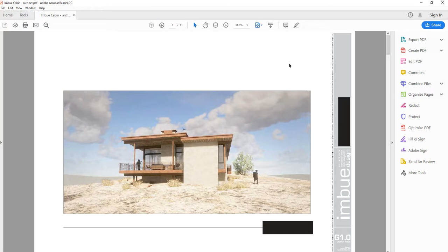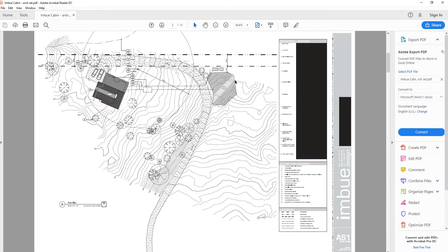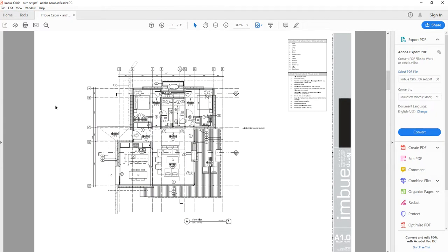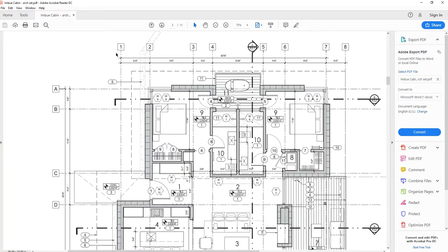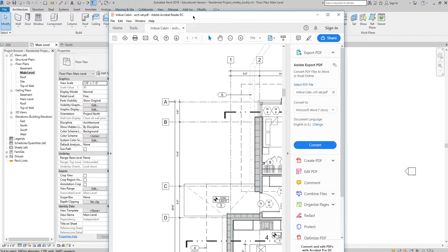And you've all taken a whack at getting some walls drawn in here. But what would have been really helpful is if you had known, and I knew this going into it, you wouldn't know how to draw grids yet. But going into it, grids would be very helpful, right? So a lot of these walls are really kind of defined off this grid. So how do we use that grid? Number one, how do we draw it? And then how do we use it to help us draw the walls in the right place? So I want to talk about that today.